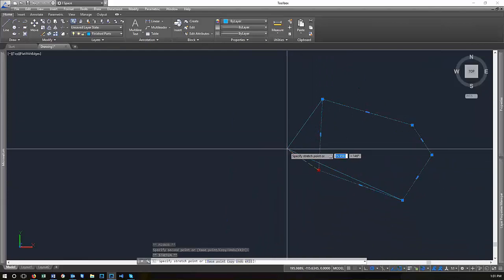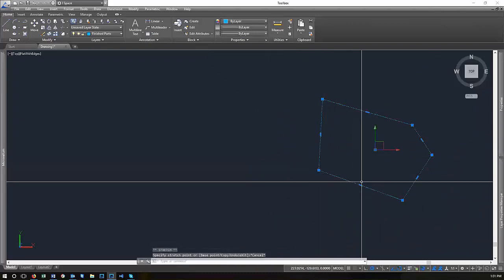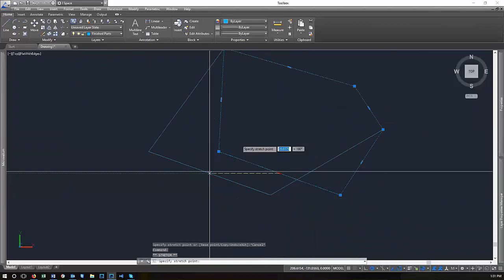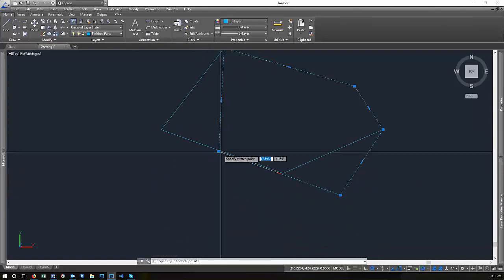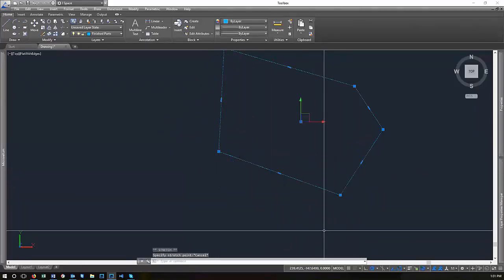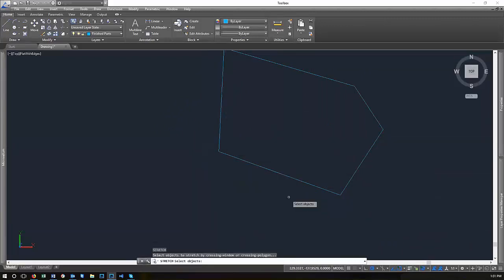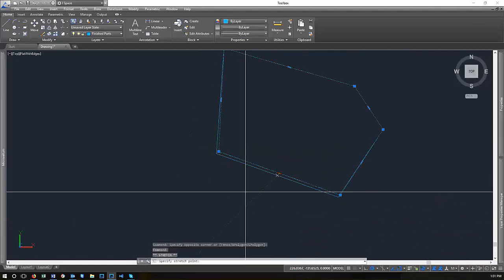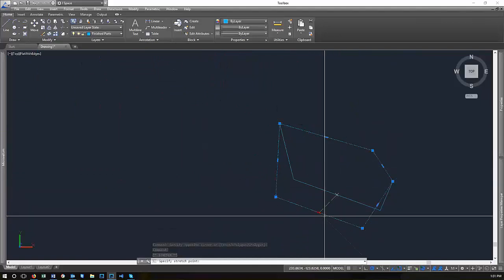So those are the basic modify commands, which we've already taught you about, but that's another way to access them, and it could be faster, it could be easier to remember. And then if you grip the midpoint, you've got the stretch command again, and it stretches the 2 points on that line. So it's the same as if you hit stretch and then grab that. But with this one, you get to specify your base point, whereas with this one, you have your grip and you're going to drag it. So these are all of the points where you could interact with your object.